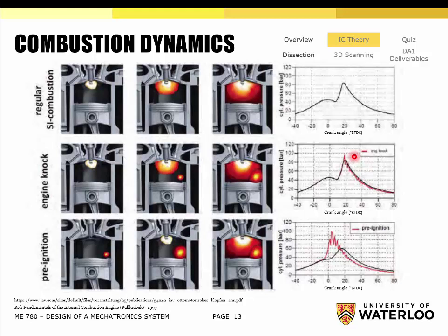As soon as it senses that, it says, okay, we must have some issue with the engine, reduce the output a large amount until we regain proper function. So it has a series of small microphones that detect that resonating frequency of the pressure signal. Does that make sense? So when you have two competing combustion events, they're not really explosions, it rings inside the cylinder at a different frequency, and there's a microphone that reads it, analyzes the signal, post-processes it, and does some decision making based on that.